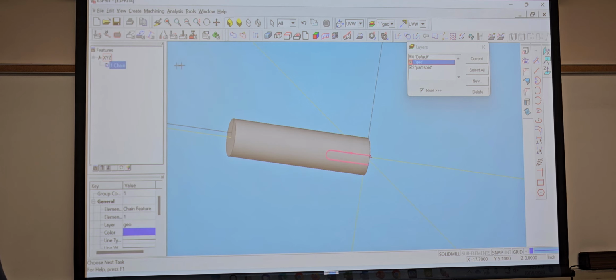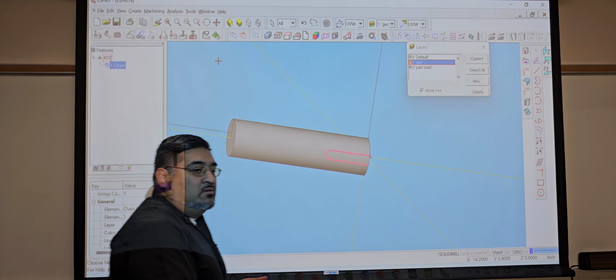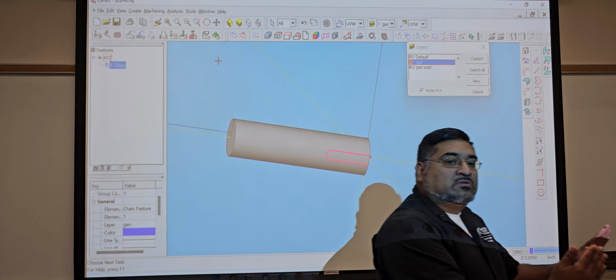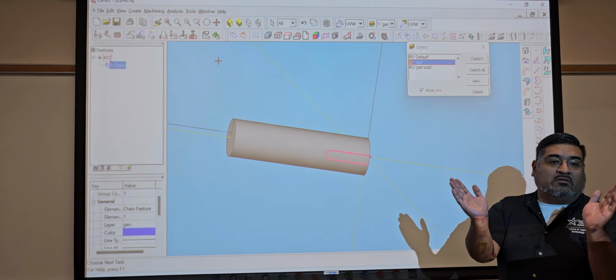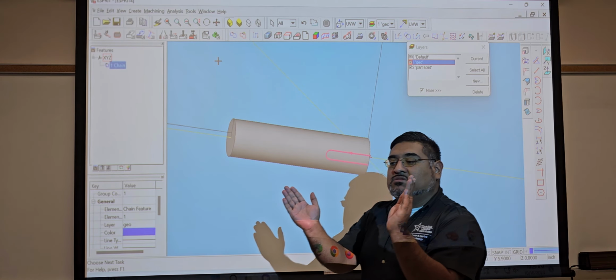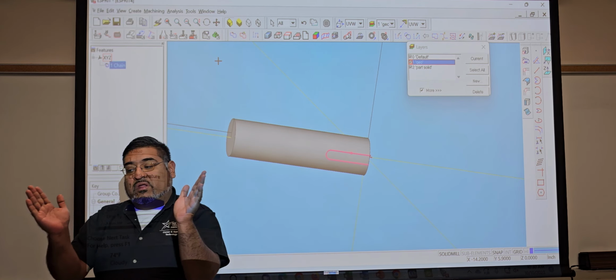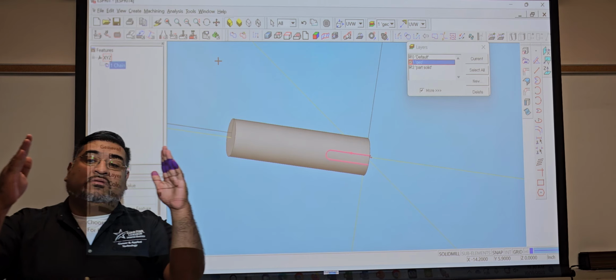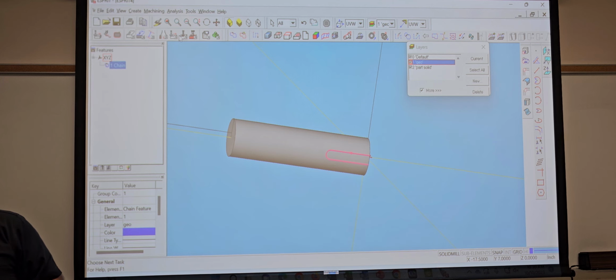Now I'm gonna highlight it, and since these are all the way through straight, right, flat on the walls, we're just gonna do contouring. Like Bill said earlier, if these actually had like a V coming down on it, then we would use the wrap one because it would have the angle to it, correct? But as we can see on the print, it doesn't have it, so we're just gonna go straight up and down, right? So all we're gonna do is click on this one, SolidWorks Traditional, and go to contouring.